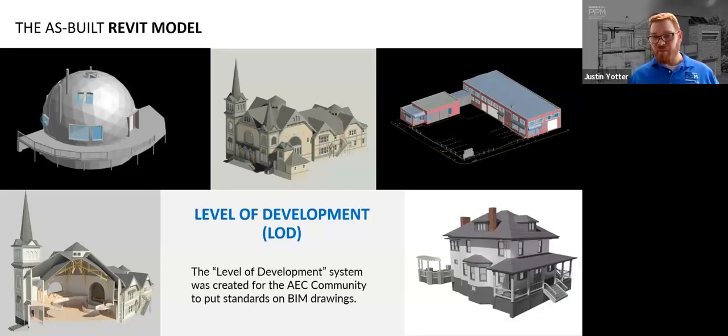When modeling as-built plans, LOD 200 to 300 seems to be the applicable range, since you are assessing a structure that has been built from the outside. All interstitial spaces are inaccessible, and their construction cannot be assumed.